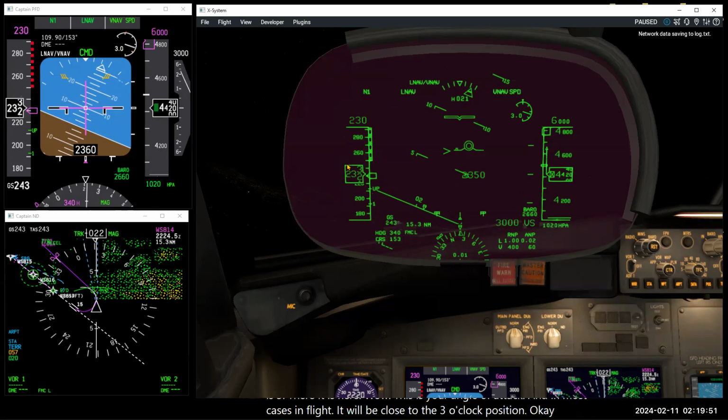The thing about HUD is, when you're taking your training, HUD is all in one color. Your brain has to accept that. And if you're at all unsure of the understanding, then quickly look at the PFD. It's giving the same information, but it's information that you're used to. It's all in color. So part of this upgrade training brings you back to your initial flight training with respect to heads-up display.